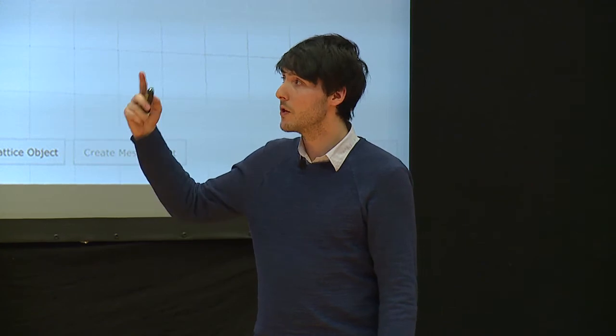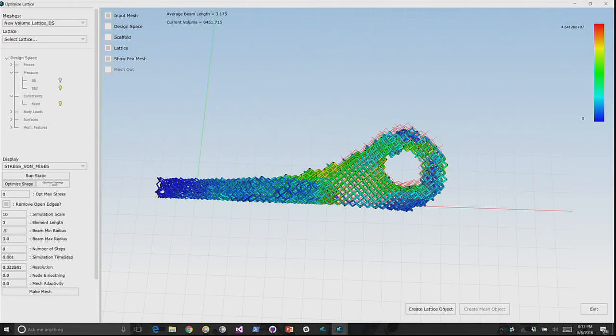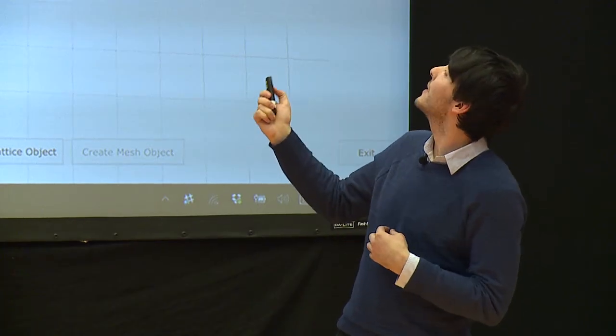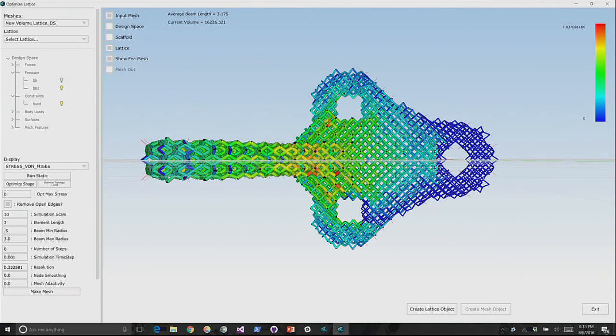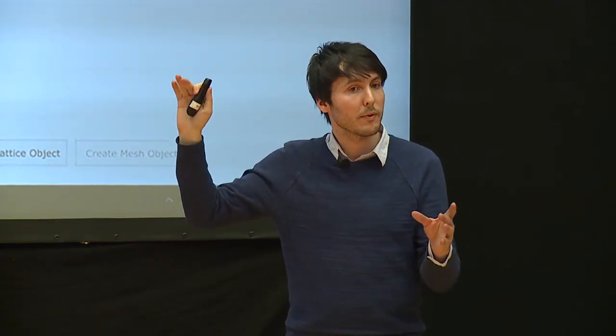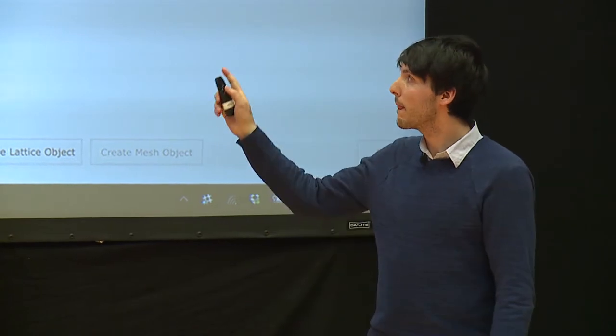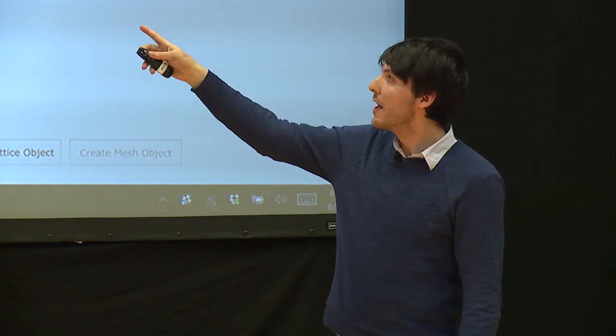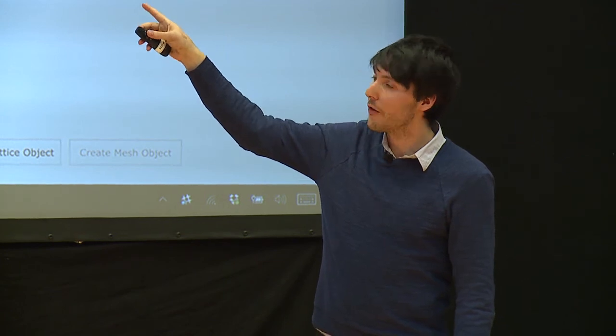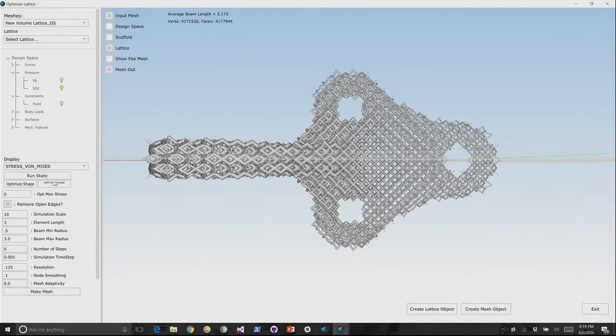And then the program is going to run through and iterate and try and figure out what the best shape is of the beam. So this is after 200 iterations. I think the max stress is like 4 times 10 to the 7th pascals. And then that's going to keep going down. So 1 times 10 to the 7th, 7 times 10 to the 6th, et cetera. And you can see it's changing, in this case, just the shape. It can also run on topology to try and optimize the thickness. And this was a part that we put through material testing. And it's funny because it was actually almost the exact same beam in that region that broke when we were testing it. And then you would extract a mesh and print it in that case.